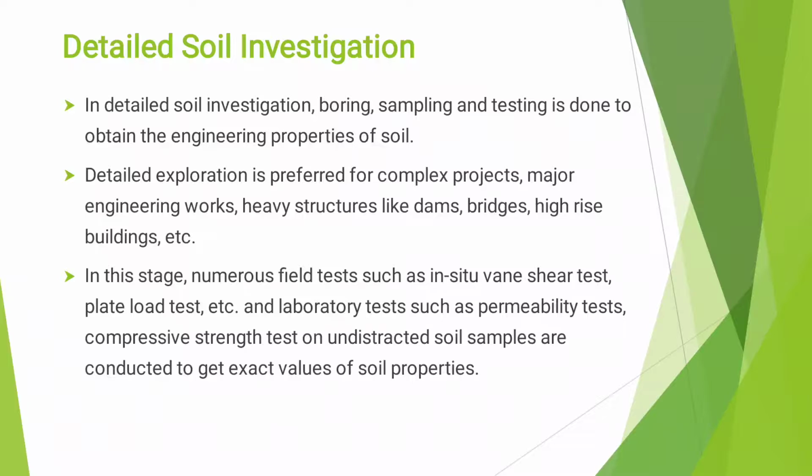Detailed exploration is preferred for complex projects, that is, major projects such as heavy load structures like dams, bridges, high rise buildings, etc. In detailed soil investigation, various field tests such as in situ vane shear test and plate load test, and laboratory tests such as permeability and compressive strength are conducted to get exact values of soil properties.